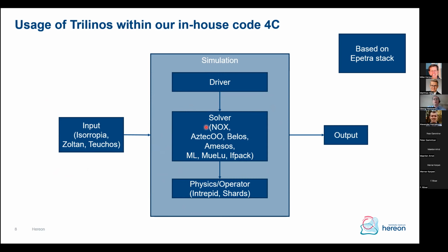At some points we use the NOX linear solver and nonlinear solver, and mostly it's still the AztecOO linear solver for iterative problems. In some parts we use Belos, especially if we have several right-hand sides, and Belos is of course interesting.